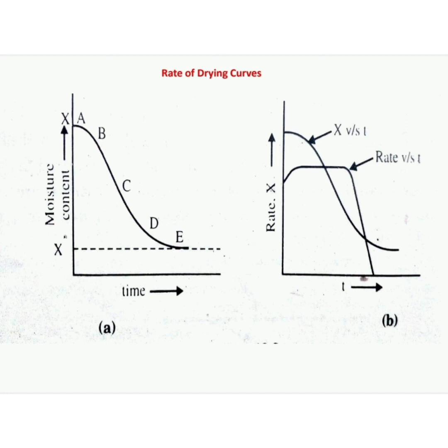This curve is much more descriptive of drying process. The rate of drying gives the relationship between rate of drying expressed as the moisture evaporated per unit time per unit area of drying surface and moisture content on dry basis. This curve can be constructed by measuring the slope of tangents drawn to the curve at various values of moisture contents, then calculating the rate.